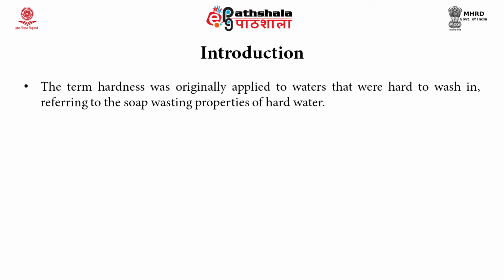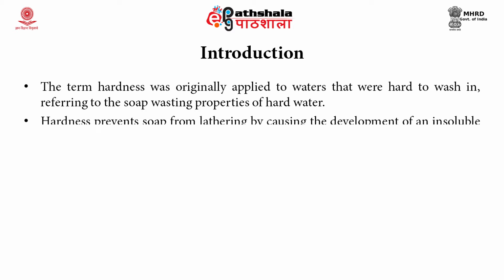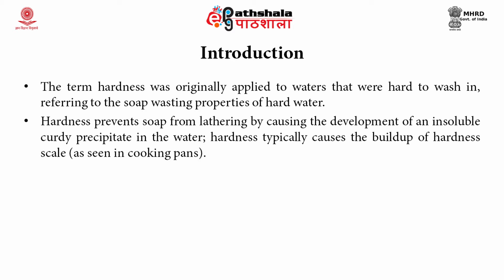The term hardness was originally applied to waters that were hard for the purpose of washing. It means they are not forming the foam with the soap. The hardness property of the water prevents the soap from lathering by causing the development of insoluble curdy precipitates in the water, and this hardness typically causes the buildup of hardness scale, which can be very easily seen in the cooking pans which are used for the boiling purpose.